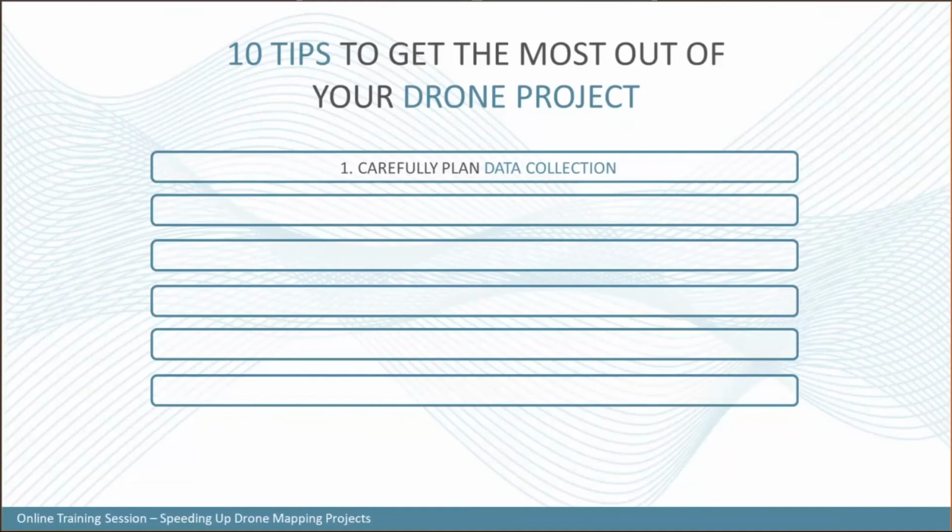Have a proper data collection, since this will have the most impact on your photogrammetric processing. One other thing: clean input data prior to processing. Having clean data before starting your project will highly reduce your human interaction with the software, since it should reduce the amount of editing you'll need to do for your drone project.